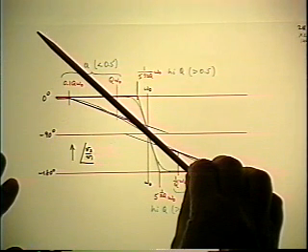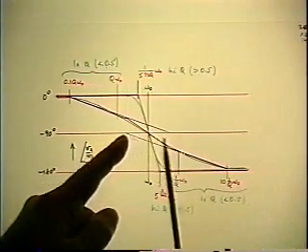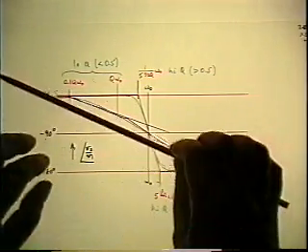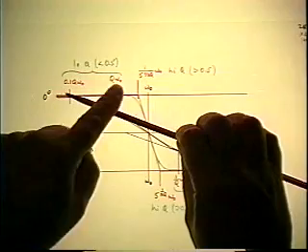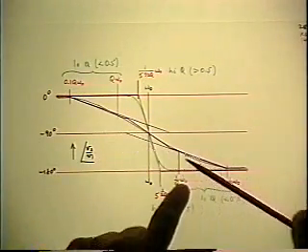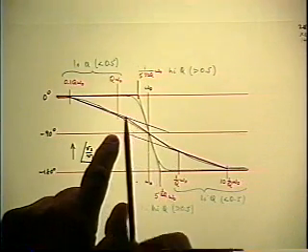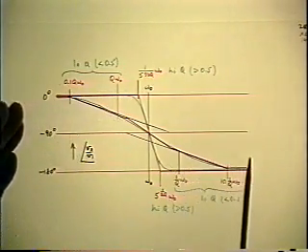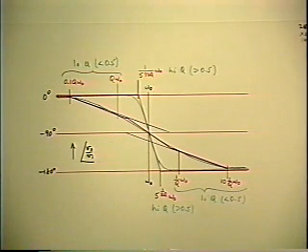namely a minus 90 degree per decade phase asymptote. As Q drops below that transition, the two corners separate equally on either side, each one taking the minus 45 per decade slope with it. So here's the one that goes to the left. There's the minus 45 per decade slope that goes with it. Here's the one that goes to the right, taking its slope with it. And initially there's a large overlap where you have the minus 90 part of it per decade again. And the lower the Q gets, the further those separate. The overlap eventually goes away. And you have the two completely isolated real roots, each with its own minus 45 per decade slope.